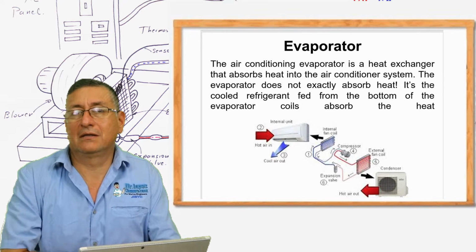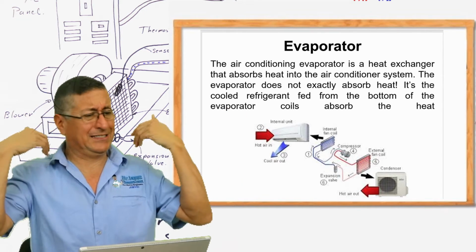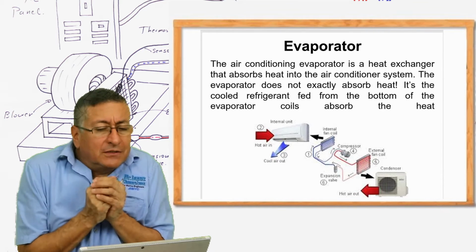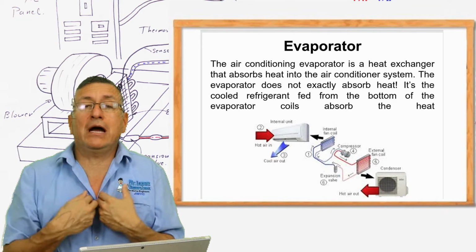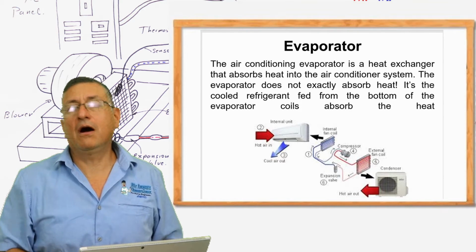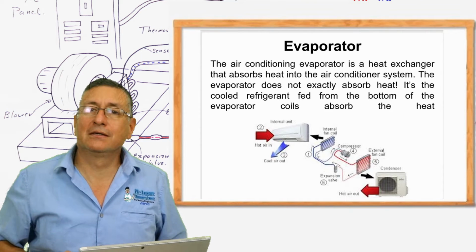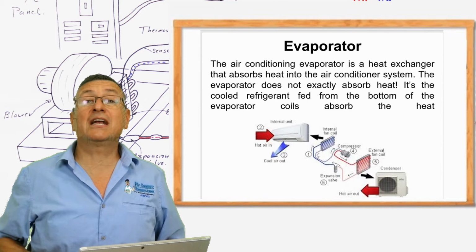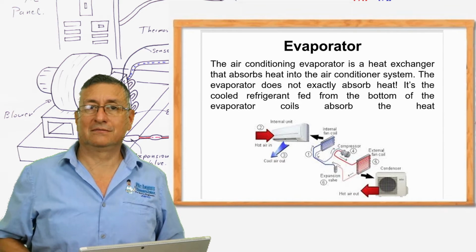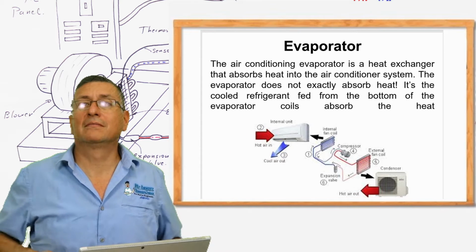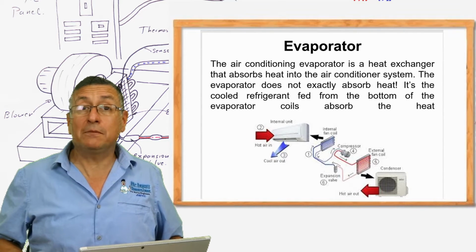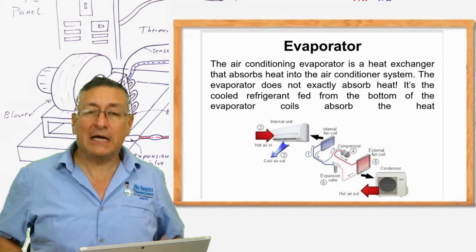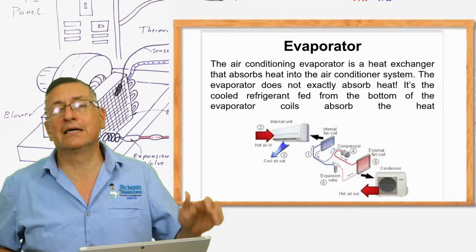This is the boiling point. Of course, at the ambient temperature it is vapor, 100% sure. But it's too low. The temperature is practically frozen. For you and me, it's frozen. For the refrigerant, it's too hot. Yes, for the refrigerant, in the output of the evaporator, the refrigerant is superheated. Yeah, it's completely vapor. If you touch that pipe in the output of the evaporator, it's too cold. But for the refrigerant, it's too hot.